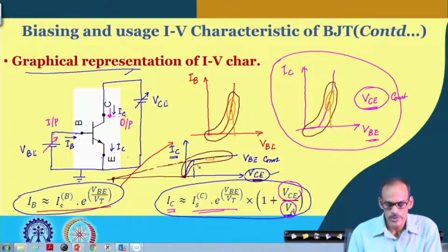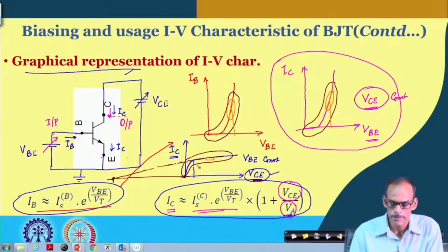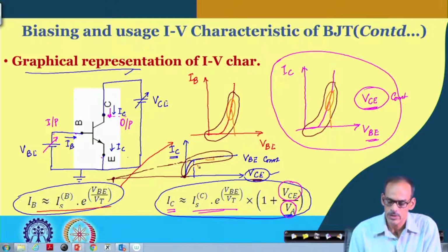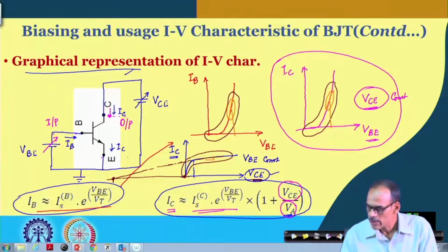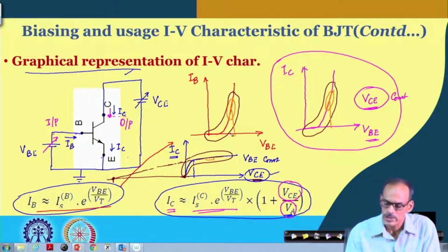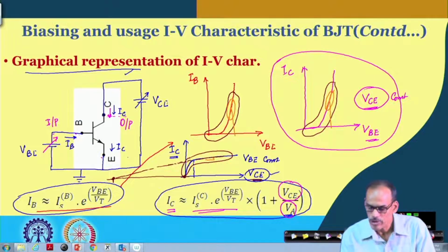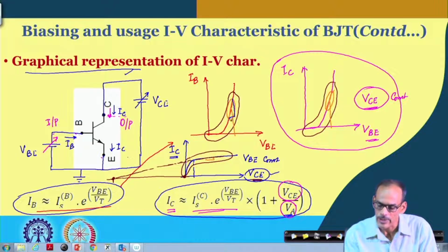As we will be using this circuit, particularly BJT as an amplifier, particularly for analog circuits, we prefer to restrict this nonlinear characteristic within a certain range, ensuring that the linear behavior of the input to output relationship is getting maintained. And we will also be seeing that apart from this large signal behavior, what is important is that the slope of this line is very important.